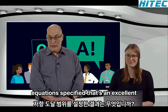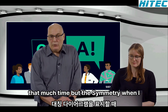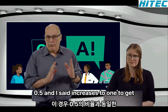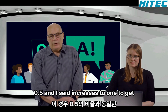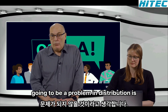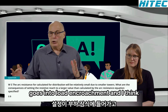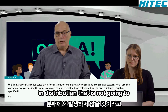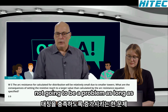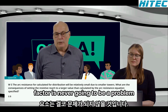That's an excellent question, I think, because there was not that much time. But when I showed the symmetry diagram, I said that I had, in that case, a ratio of 0.5, and I said increase it to 1 to get it to an equal value. The only risk, and I think this is not going to be a problem in distribution, is that your very large resistance setting goes into load encroachment. And I think in distribution, that is not going to happen. So setting a larger resistance is not going to be a problem, as long as increasing it to meet the symmetry factor is never going to be a problem.